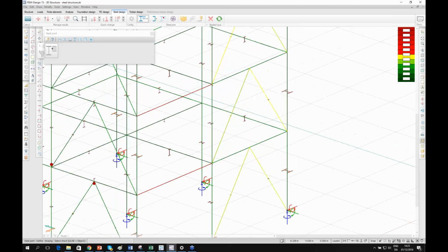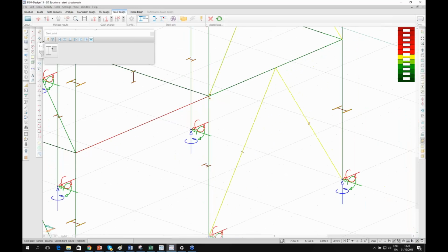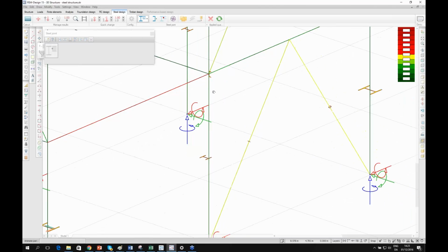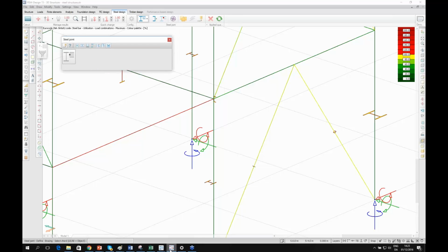No matching solution found. This can be for several reasons. Also, the physical alignment of elements needs to be correct and match the type of the connection in the steel joint module. Let's see.